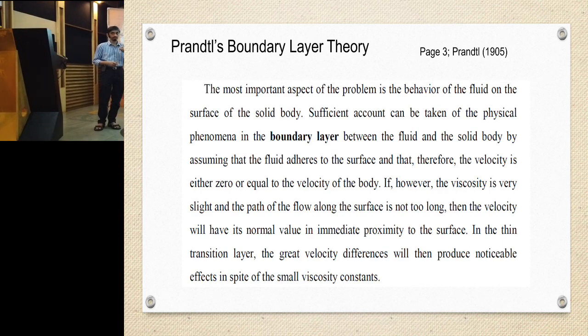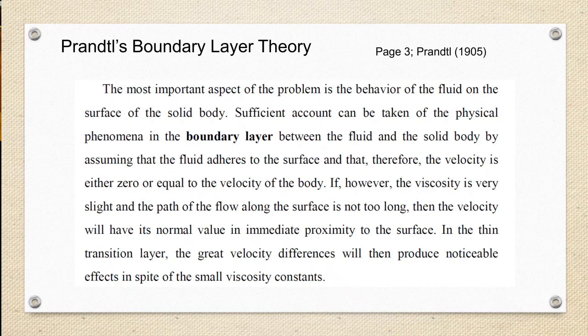They don't stick to the surface. Okay. But that slip velocity is so small that you can essentially neglect it. So the no-slip condition within the continuum hypothesis is really an approximation. You should remember that. But for all practical purposes, and also for all theoretical purposes, within this approximation, it works very well.